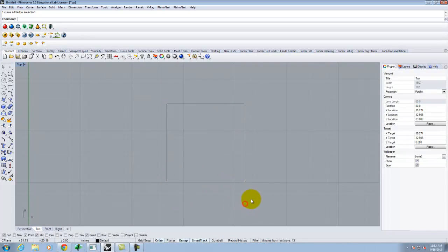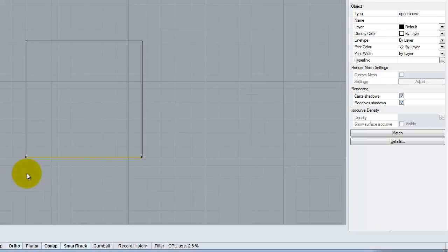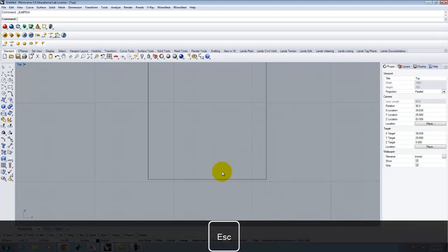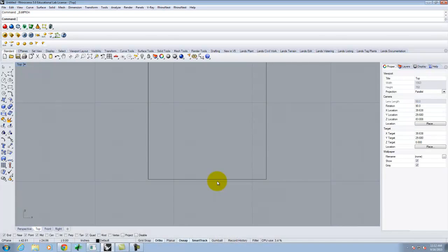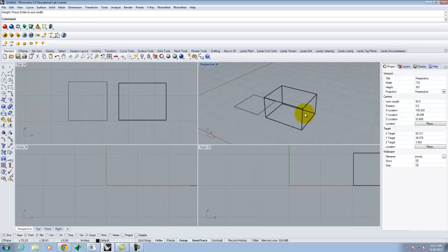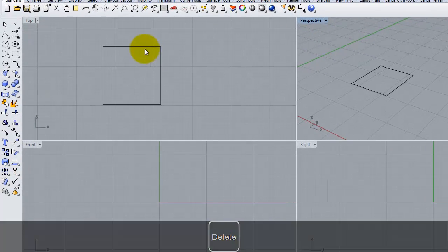Now, if I were to look at the control points that define these curves, basically I have 2 on each of these curves. So let's look at one for example, and I'll turn on the edit points, and you see that at the end of each of these I have a point. I'm just trying to show you that there's a control point on each end. I want to change that so that I have some more flexibility with what this curve looks like. Obviously, if I wanted a straight square cushion, I'd just do the square, and I'd make a cushion that looks like that, right? But I don't want it to look like that. I want it to be far more organic in its shape. So I'm just starting with the square.